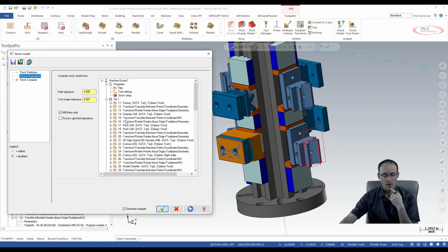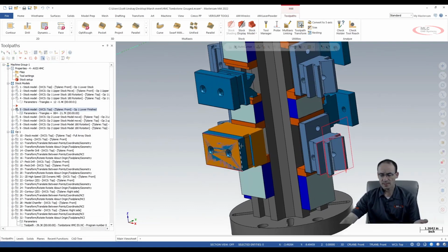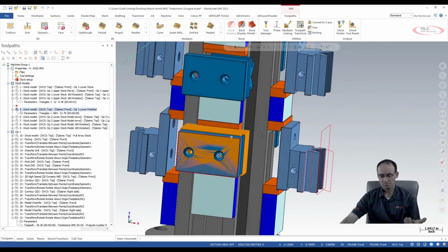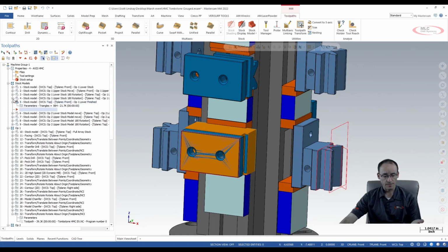And I've picked all of the tool paths in here that are for Op1 without the transforms, because I could pick them, but it would just add generation time that's not doing anything for my stock model. So I'm going to bail out of that one, and this is what I've got. It's drilled the holes and it's cut the outside, and we've cut this little slot that we wouldn't be able to reach when we're on Op2. Okay, so now I've got my Op1 finished, so I'm done there.